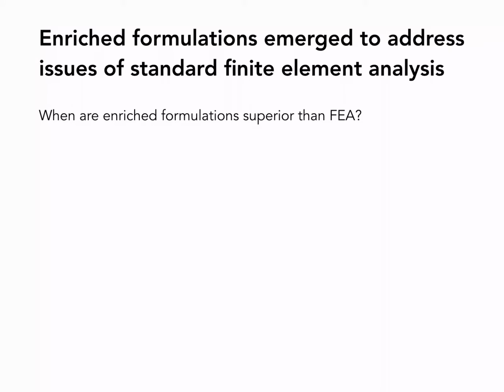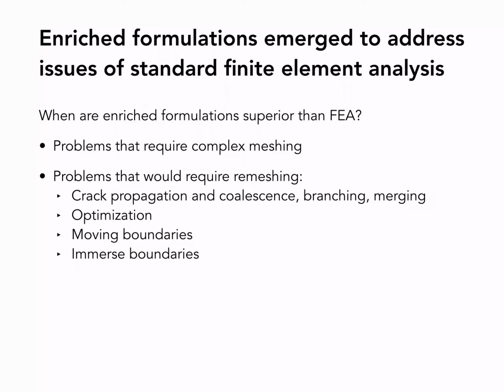So what are the problems where enriched formulations are superior to standard FEM? Because of course every method has its strengths and weaknesses, and so we want to identify what are those problems that we can actually use enriched formulations for. There are problems that require complex meshing. So imagine you have a complex object, and it requires really heavy meshing, and you don't want to handle that meshing at all. So in a way, enriched formulations can be used to transfer that complexity from generating the mesh to the formulation itself by means of a geometric engine. I'll show you a bit of problems like that.